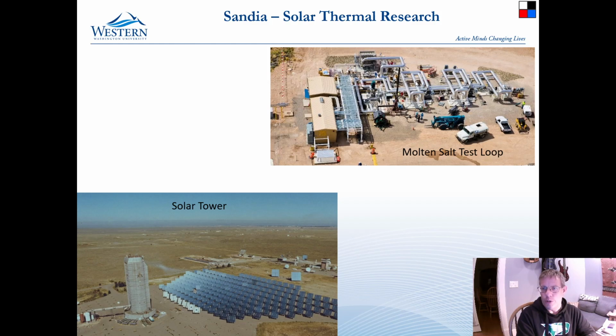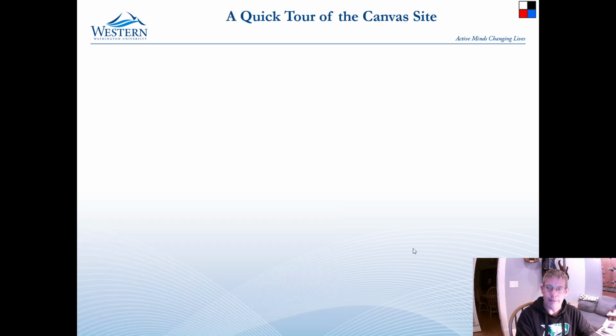So how do you do a weld in these things that will be able to take on that kind of motion and that kind of expansion and not just come apart? It cannot leak, because if the molten salt leaks, it ruins the system that it's in and then freezes up, and it's nearly impossible to get off. And so you have to build this thing and know that it's right before you ever put salt in it. So that's pretty challenging. All kinds of neat challenges that I did with that.